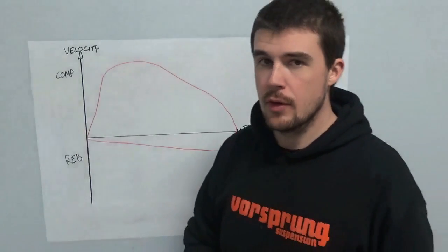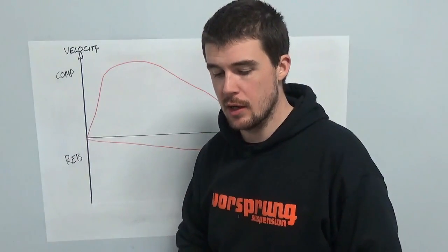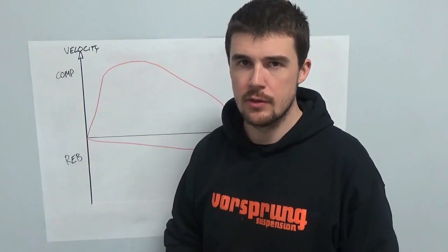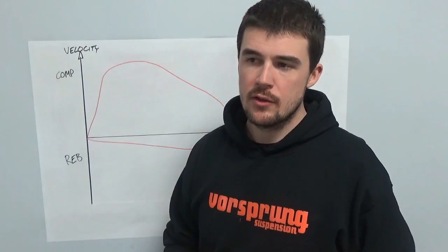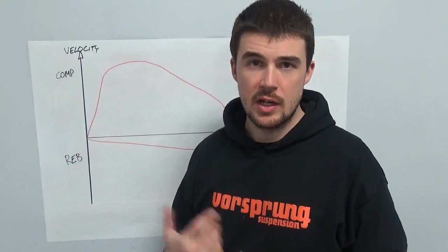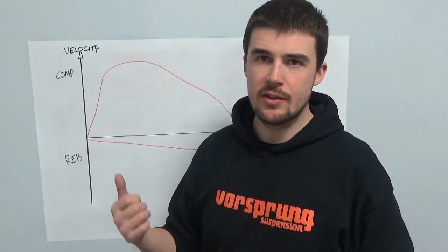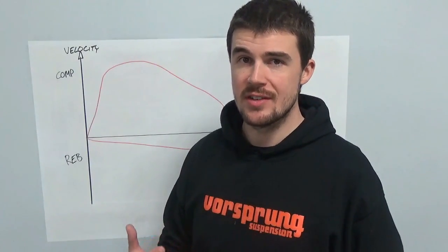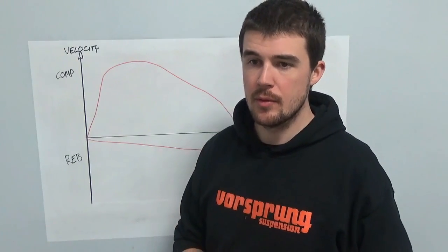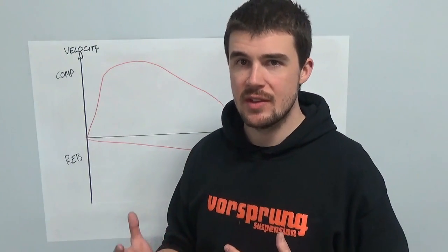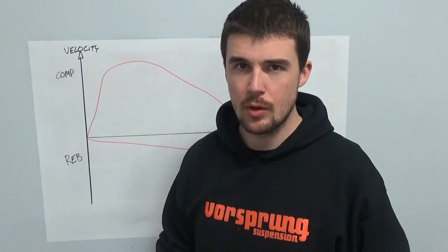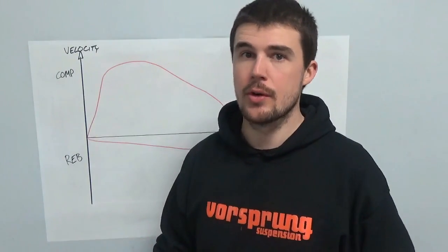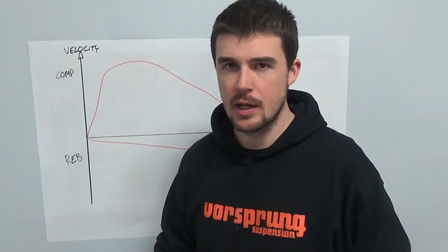So what we've seen advertised here and there over the years is speed sensitive damping, which is basically any shimmed valve, popper valve, whatever, anything that isn't an SPV or boost valve setup, that is an inherently position insensitive damper. But speed sensitive damping that will give you a plush initial stroke but ramp up to resist bottoming out.